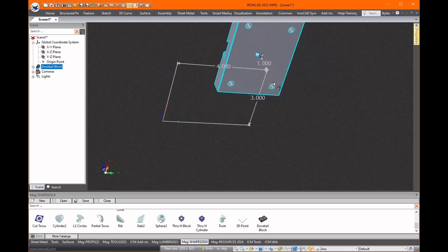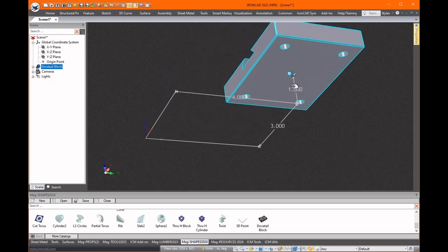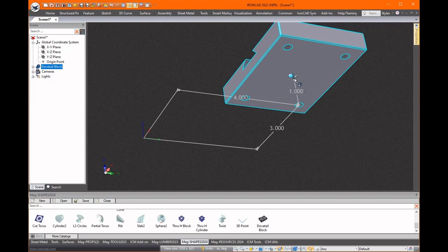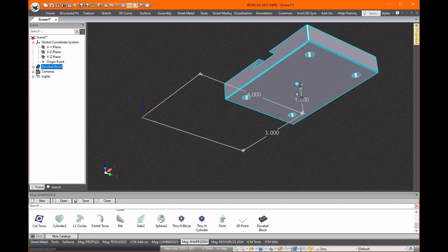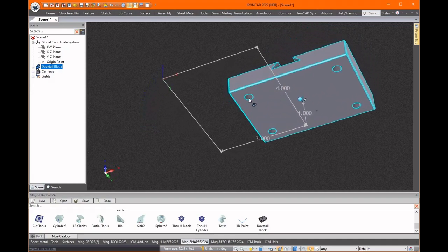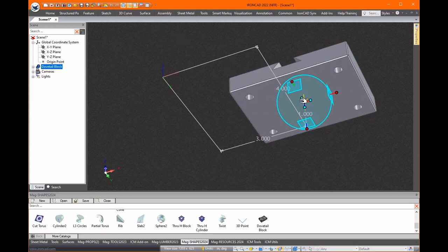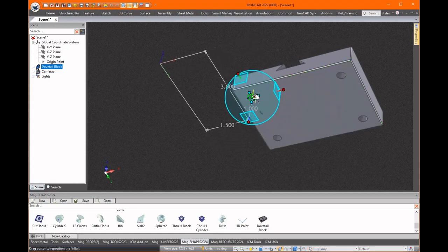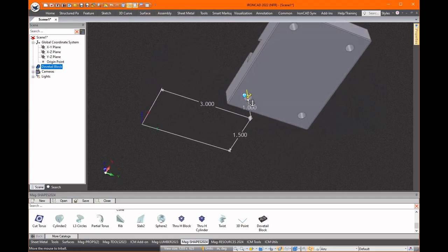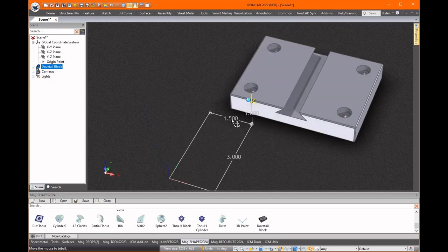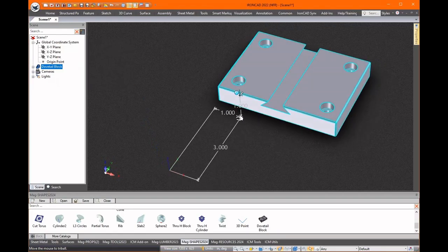These position dimensions are attached to the anchor of a part or assembly, and that's where it'll draw these dimensions from. So if you wish to have a key point on your part from which to derive these dimensions, simply click the anchor using the tri-ball and drag it to the desired point, and you can see now your positioning dimensions are based on that key point of that hole, where you can come in and continue to edit.